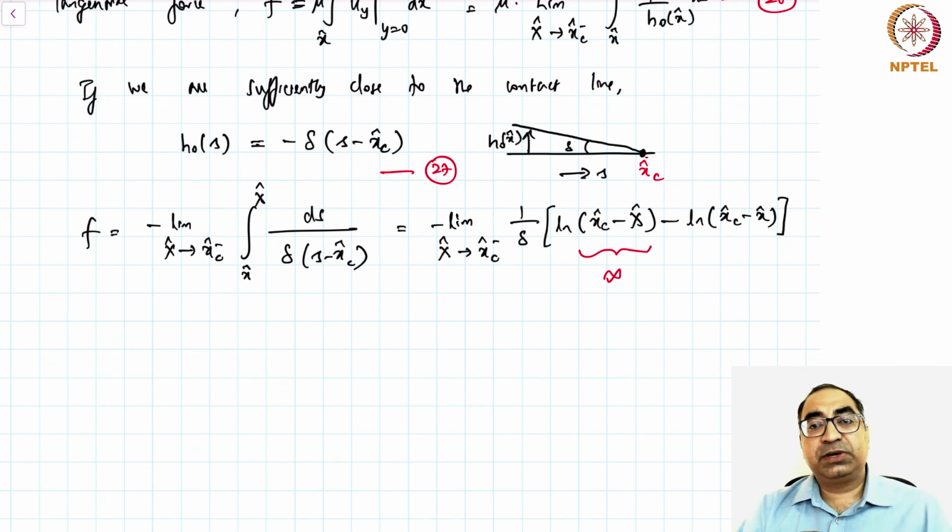This also is true for, let's say, a droplet moving down an inclined plane. If you have a droplet moving down an inclined plane, there is a singularity at the contact line. If you apply the conventional boundary conditions, then it means that I need an infinite amount of force to make the droplet move. But we know that is not the case. If you just blow a puff of air on the droplet, we know that the droplet will move. So the force is clearly not infinite. Therefore, there is a paradox in some sense, right? So how do we resolve this paradox?